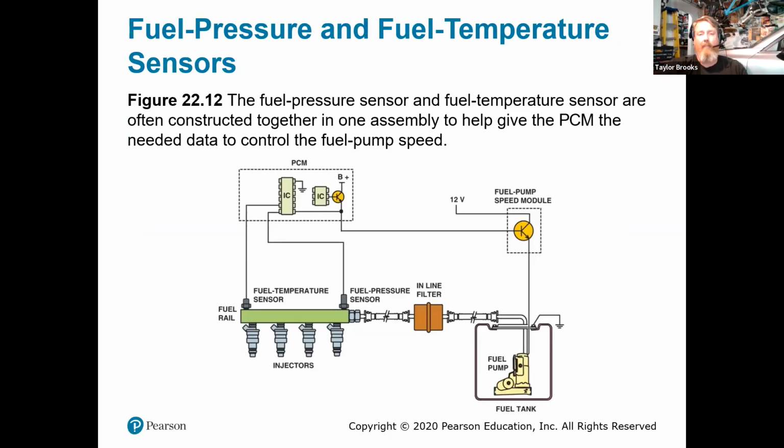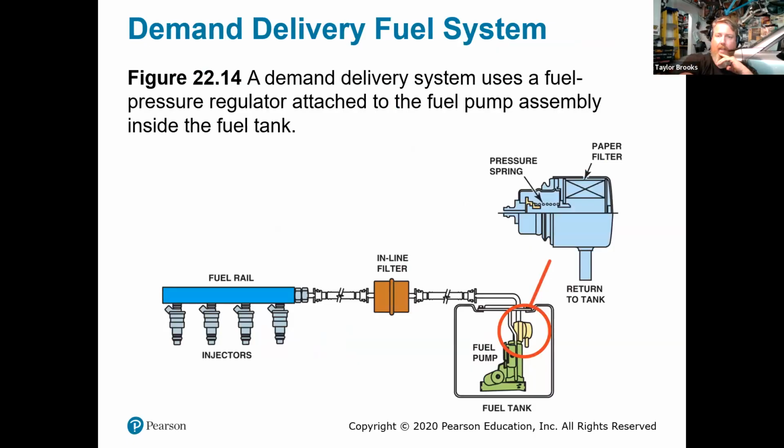Now, we do have to have fuel dampeners installed on the fuel rail when this is the case, and that is because anytime we pulse width modulate anything, we can create a harmonic. What we're not trying to do is send that harmonic to basically press the fuel back. So we have a dampener that, every time that pulse of fuel comes into the rail, takes up that slack so that we have consistent pressure throughout the rail the entire time. This can typically be found on the fuel tank or fuel pump in the fuel tank, but can be found on the rail as well.